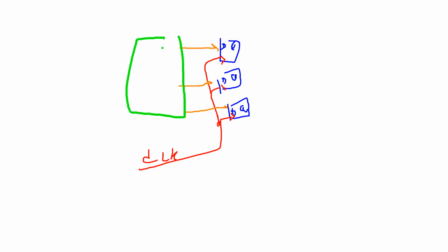For the simple case, let's use D flip-flops. The flip-flops change state when the clock ticks. For a clock synchronous state machine, we use a common clock, so all flip-flops connect to the same clock. When the clock ticks, you read data from circuit F, which is a combinational circuit.